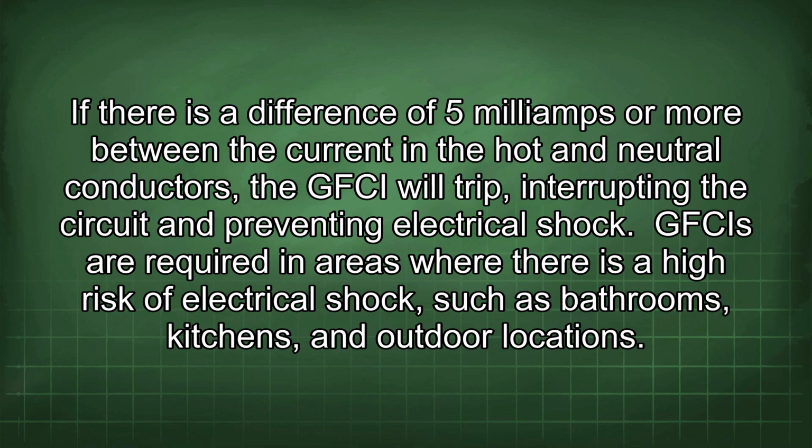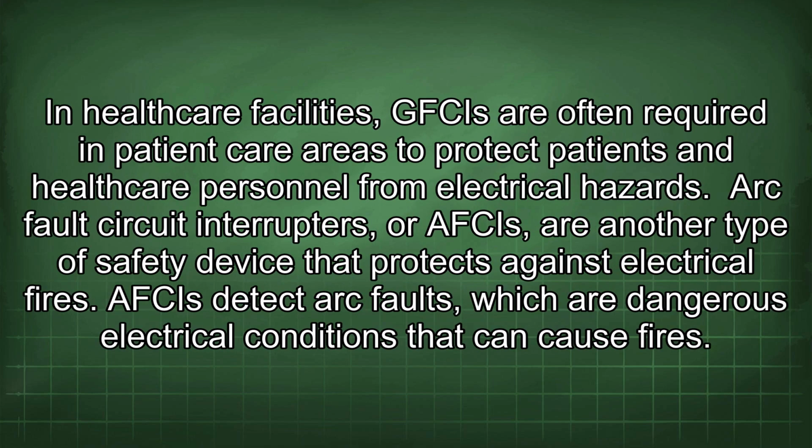GFCIs are required in areas where there is a high risk of electrical shock, such as bathrooms, kitchens, and outdoor locations. In healthcare facilities, GFCIs are often required in patient care areas to protect patients and healthcare personnel from electrical hazards.